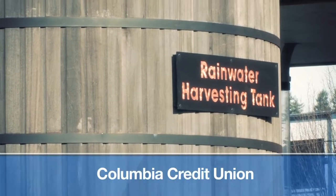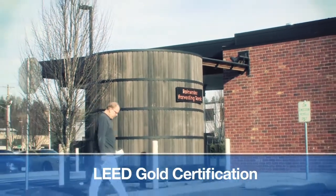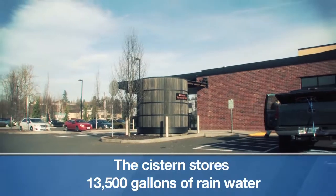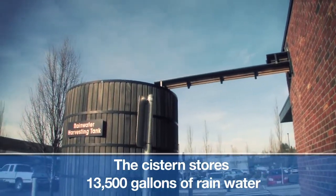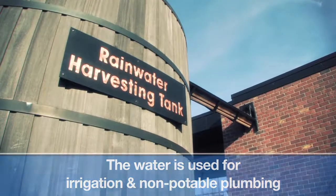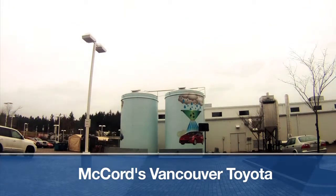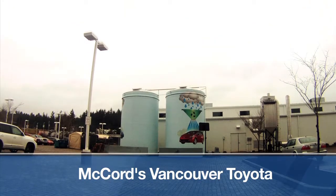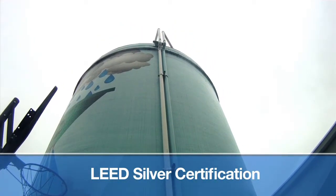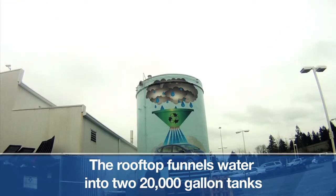Cisterns are containers or vessels that are used to store runoff for future use. Cisterns can store rainwater in significantly larger volumes in manufactured tanks or underground storage areas. Rainwater collected in cisterns may also be used in non-potable water applications such as toilet flushing. Both cisterns and rain barrels can be implemented without the use of pumping devices by relying on gravity flow instead.